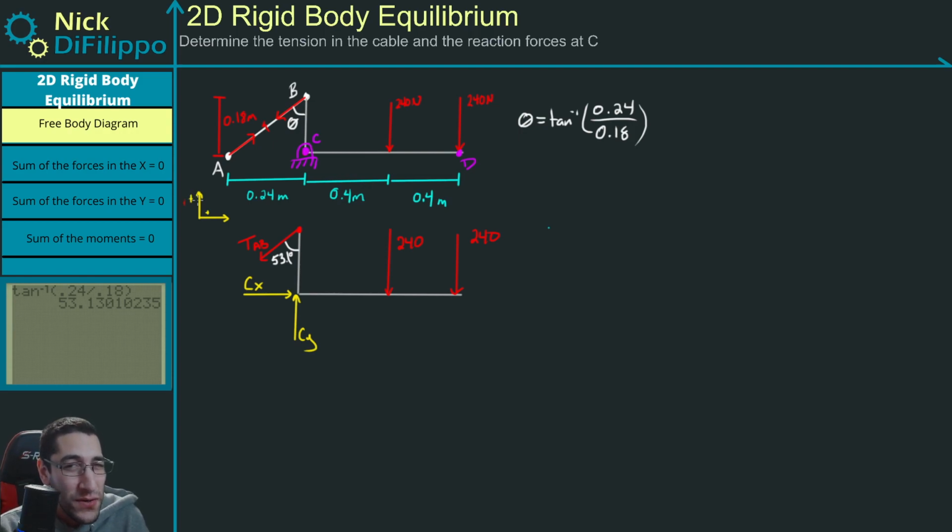We don't need to do this, but it's good practice so you don't start messing around with negative signs. So when you don't know a force, assume the force is positive. If you are incorrect with that assumption, all that means is when you solve for this force, it's going to have a negative sign and the force just actually acts in the opposite direction. No big deal.